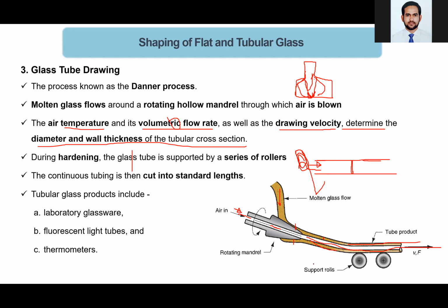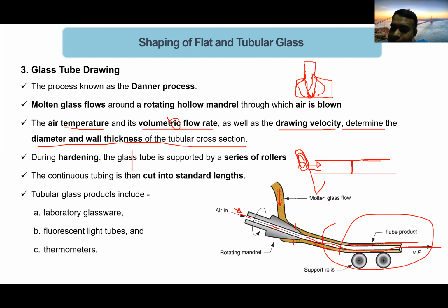And for your information, the outer surface will not be as smooth as the inner surface. আচ্ছা. Then you must have to clean the outer surface and do the grinding and other polishing things. Okay? And also when you do the annealing, after drawing you always need to do the annealing, right? When you do the annealing, then it becomes much more uniform. Okay.